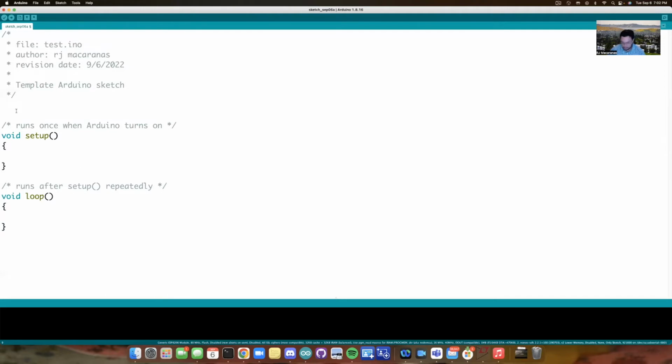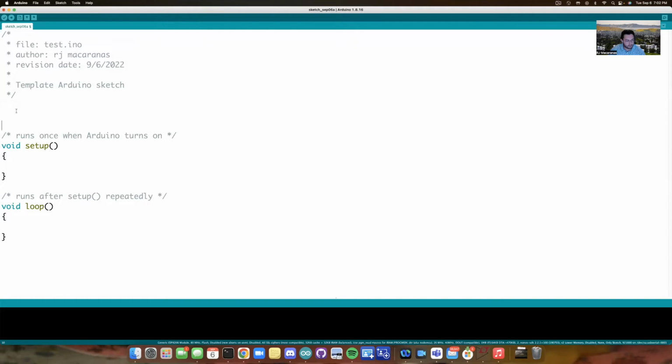Arduino was built on top of C++. And in C++, we have this construct called a pound define. It's more or less a macro, right? So we can have this LED pin, and say we're using digital pin 13 to control an LED. What comes after the pound define is the name of a variable, more or less, and this will be something that is constant.